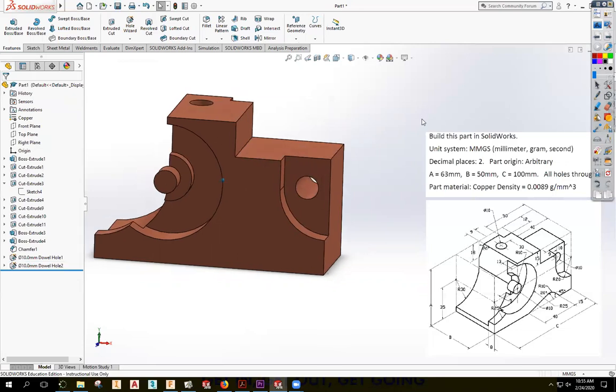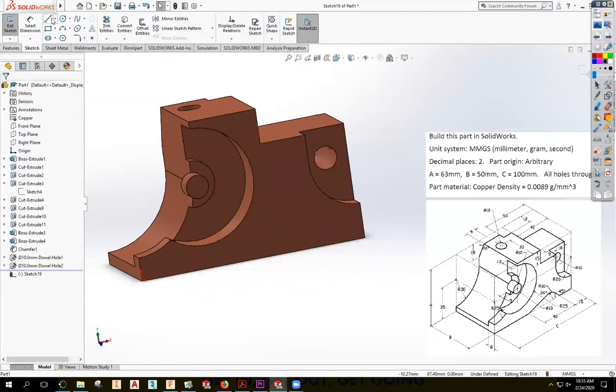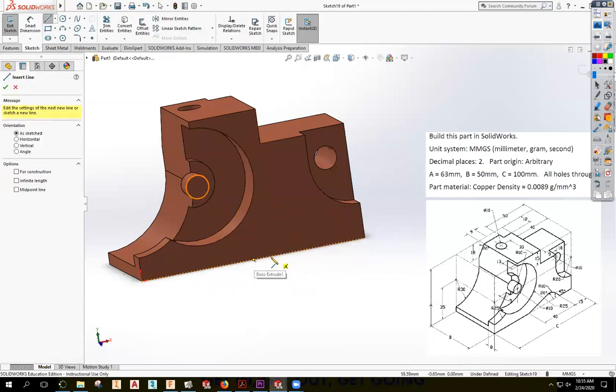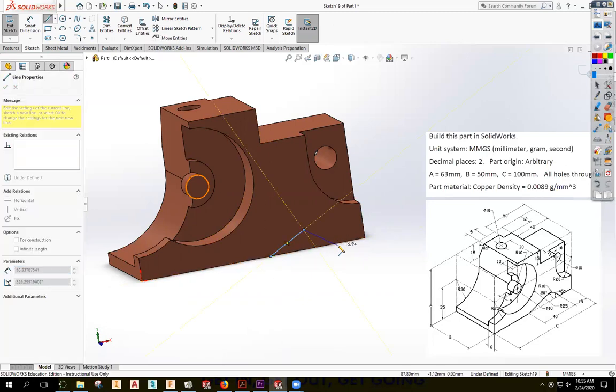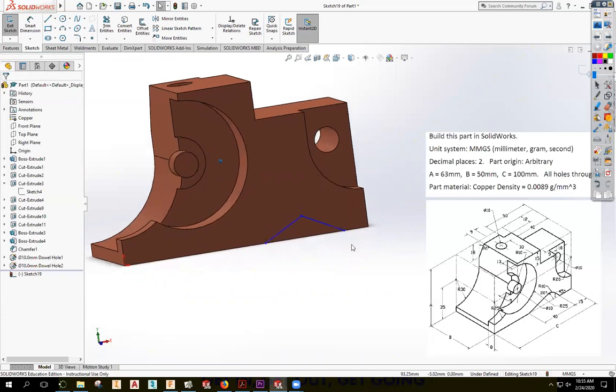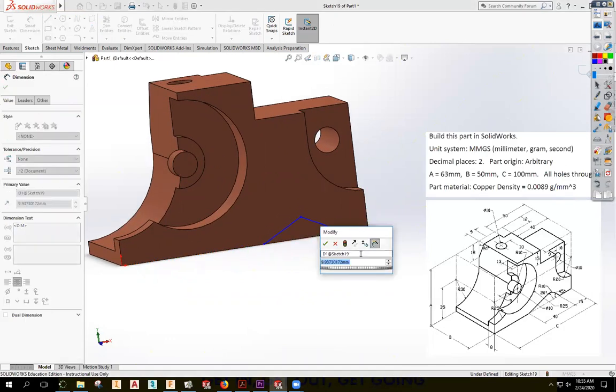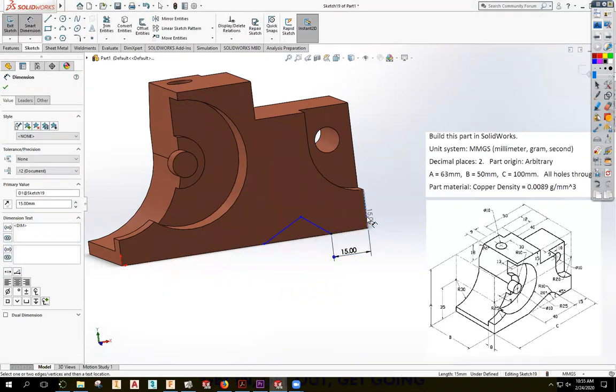And there we go. Oh, I forgot one thing. What'd I forget? The bottom. Yeah, this thing right here. So extrude cut here. Make sure I don't grab the center point or the midpoint. Just get 2 lines in there. And now I can tell it this point to there, 15.